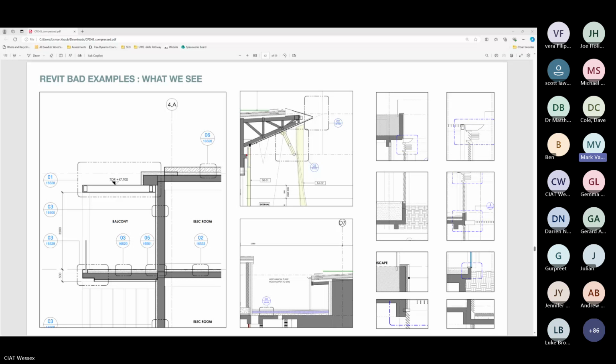Yes, that balustrade and those louvers would probably look where you want them to be in 3D. They probably look where you want them to be in plan. But when you come to the section, if you were casting your construction lines up to place those elements in, you would straight away see that those louvers clash with the slab edge, that balustrade is not connected to the slab edge or to a structural element, and that we've got steel that sits through elements. So all of that would be seen and caught in 2D straight away, and you wouldn't even draw it wrong from the start.